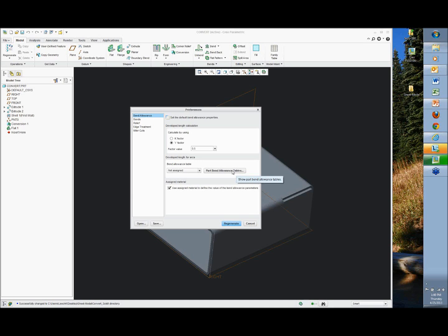But at the same time, if you're just developing sheet metal parts and you're sending them to a shop, or maybe you're sending to 5 or 6 shops to get different quotes, best bet is to drive everything with the 3D shape, give a reference for the flat pattern, and I would stop there. Because every single shop that you deal with is going to be a different size and shape.